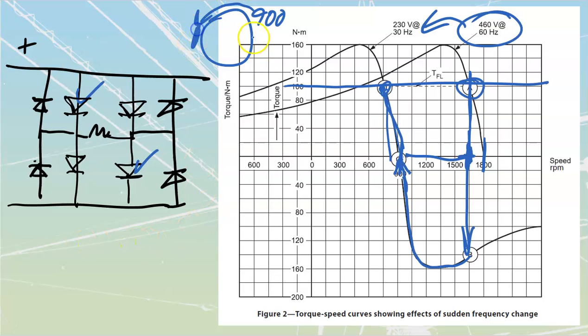Basically, it would lock my fields that are usually whipping around the stator. Now we would just freeze them in place. So we're going to have three individual fields around there, which means that the inertia that's driving the rotor through there is going to cause us to burn off heat across the rotor. This is something you can just program into the drive. The drives are not usually going to have this by default because, as we know, DC injection braking does usually cause us to overheat the rotors, particularly if it's done a lot.